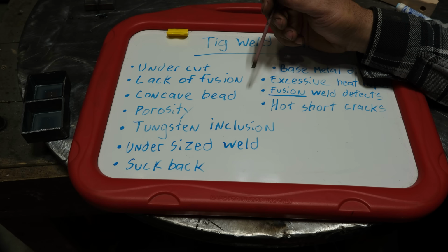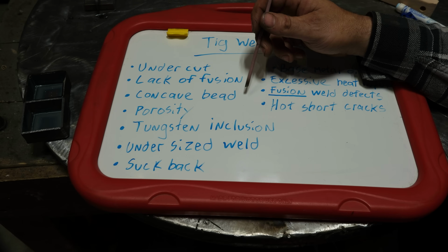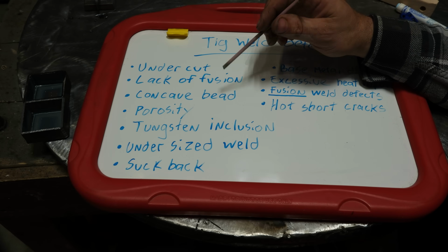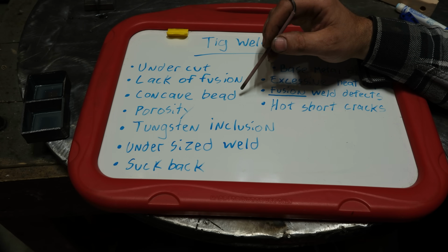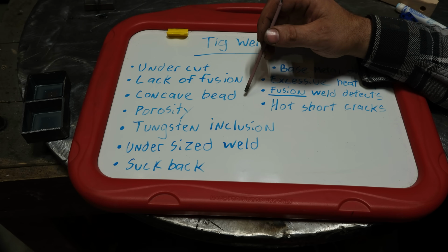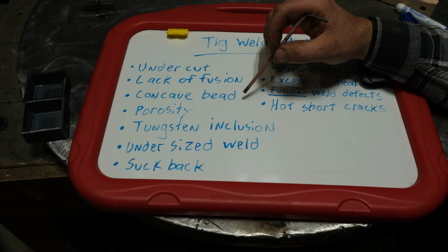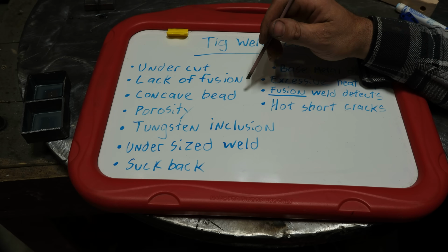One of the reasons is that the point tends to be a little bit stronger than 3/32, and if you're running it through the molten puddle by accident just a little bit, but the arc stays lit, aka the arc does not extinguish, odds are you are not going to leave an inclusion with that 1/8" tungsten. If you're using 1/16 tungsten or 3/32 tungsten, that thinner stuff, and the arc almost cuts out, it's possible that you would have contaminated something in that weld with it.